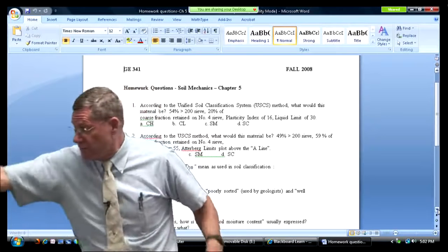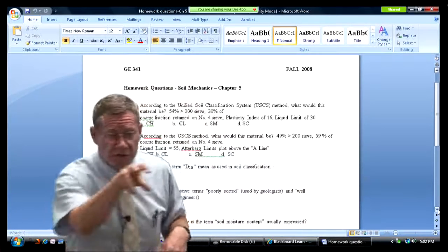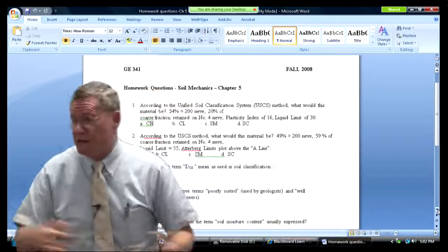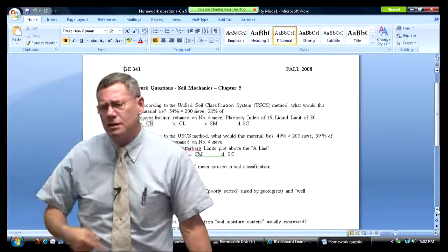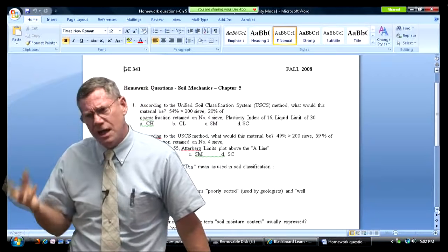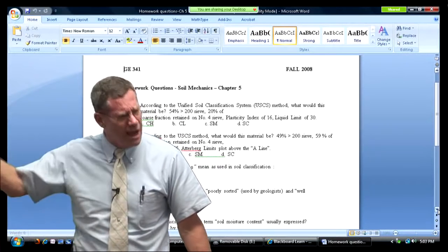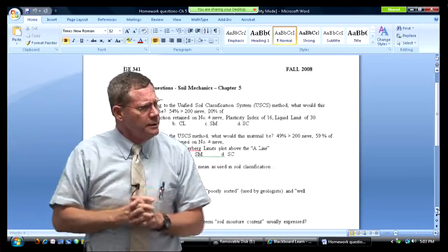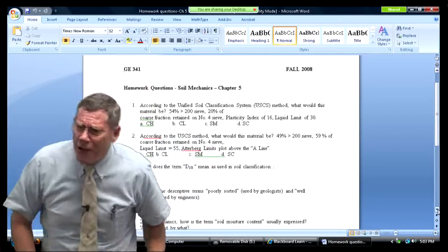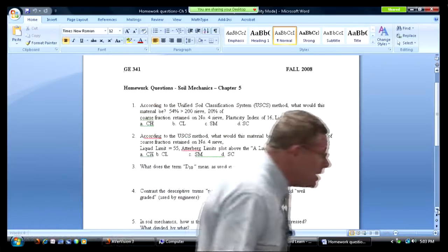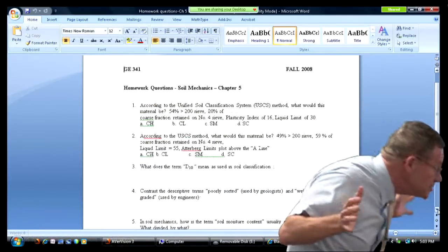You're going to have to take some stuff over here, take some stuff over there, and mix it together to get a well-graded mixture. And that fails to occur over and over because they use a canned spec done downtown in the big building, and none of those engineers likes to get dirt on their feet. So they don't actually go out and look and say, does this stuff exist?